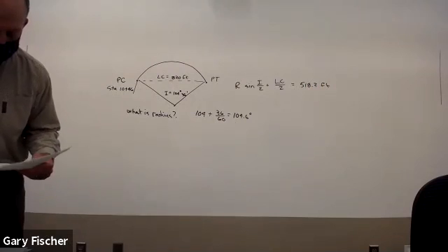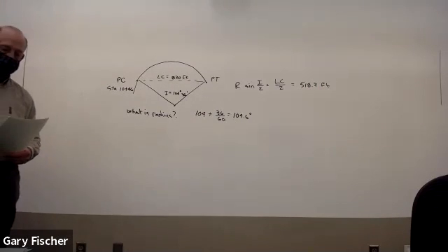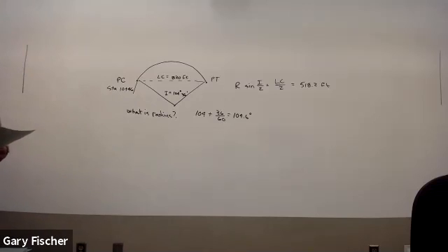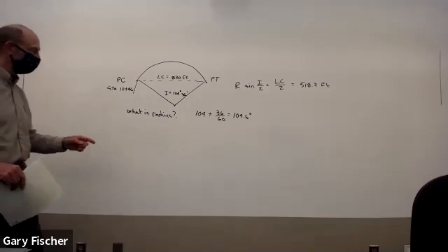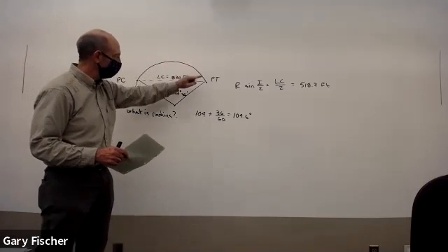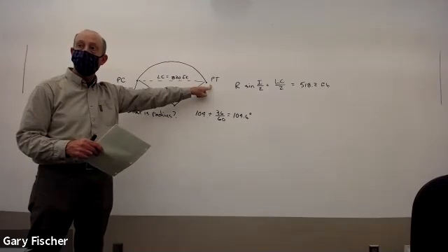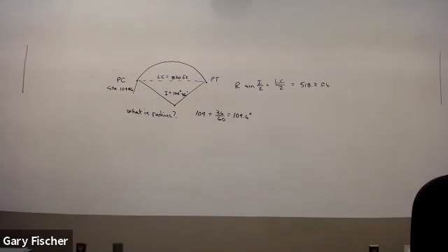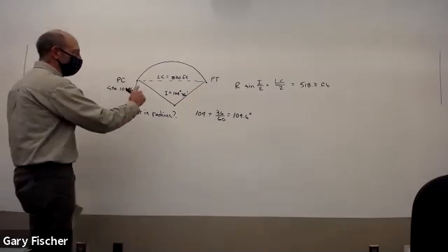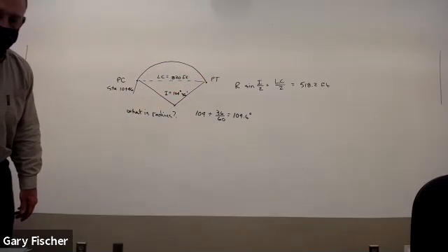That I, the 104 degrees, is that about surrounding the center point of the curve? Correct. Yep. So curves are typically identified by two endpoints, and it all has to do with stationing. You start here at the point of curvature and you travel around here. They give you the length of that curve, 820. So if you add 820 to this station, you would end up at your station at the point of tangency. And they're giving you a radius, so this is a steady radius around here. It's not a compound curve or anything like that.